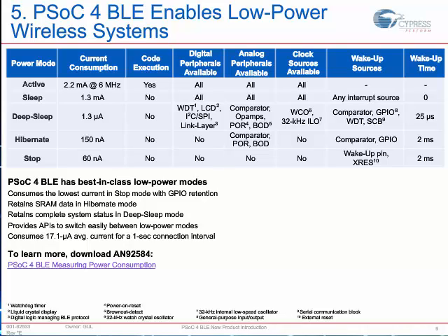For instance, if I have a sensor in a room where I'm trying to measure its temperature, I might not care for minute-by-minute updates. I could spread that over some further intervals, and in that case, not worry about taking the extra few milliseconds to establish a Bluetooth connection. Or in another example where my product is manufactured and deployed out of my factory with the batteries inserted into it, but it's sitting on a retail shelf for a long time, and I don't want the batteries to drain out when it's just sitting in this extremely low power mode.